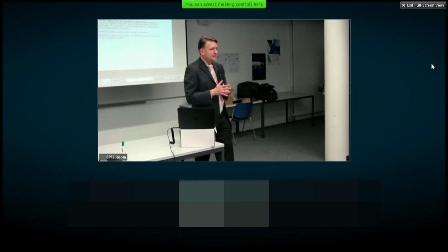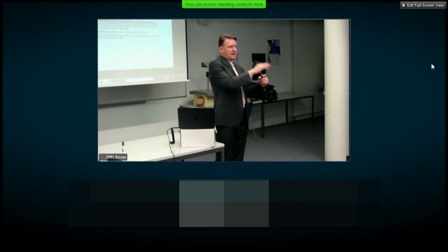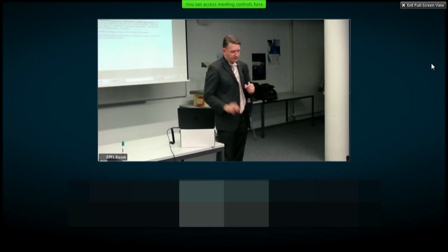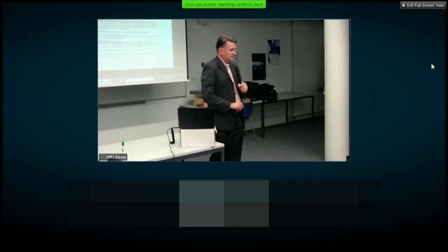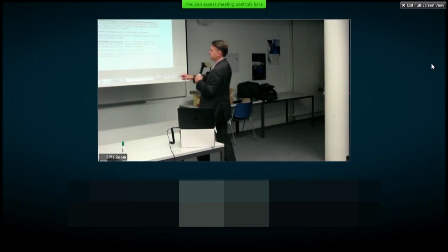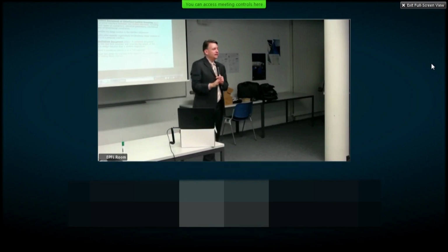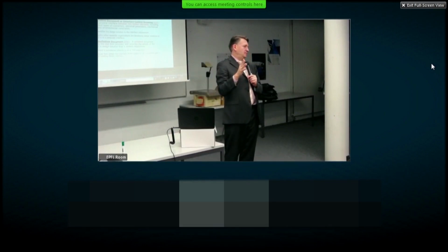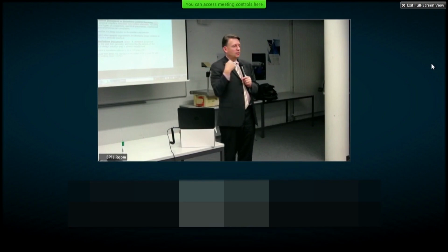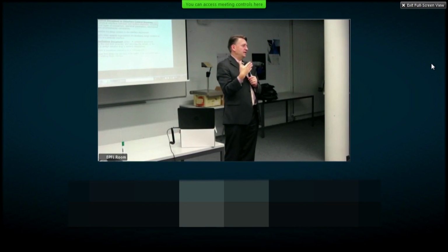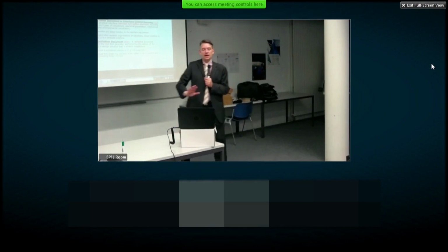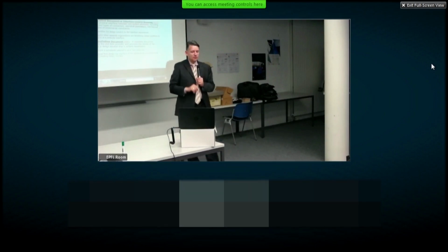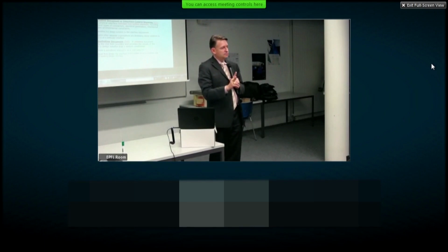The key about the ICD is that it's a two-sided document. There's a subsystem A and a subsystem B, and they share a common interface. The interface control document defines both sides of the interface, as opposed to an IDD, interface definition document, which is only a one-sided or unilateral document. For example, let's say your company makes a very fancy camera or sensor to be used on a spacecraft, but you don't know who's going to use that camera or how they're going to use it. So what you're defining is essentially your side of the interface, physical and functional, and then it's up to whoever your customer is to take the IDD and turn it into an ICD. The IDD is only one-sided, unilateral, and the ICD is a bilateral interface definition.